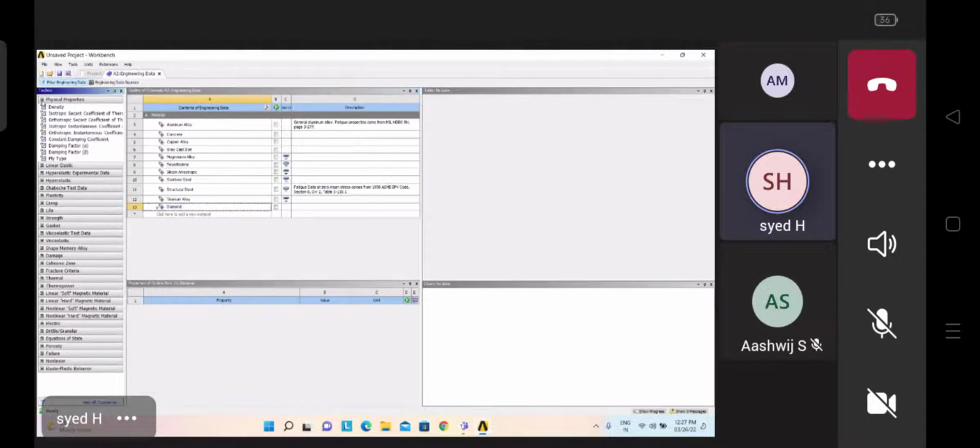First I am going for the physical properties here. For every object, density is a must. Without density it is not possible to find the solution. So I am taking the density and placing it under property. Now see here, density has been placed here. What is the density of your object? For example, I am giving here some 10,000.